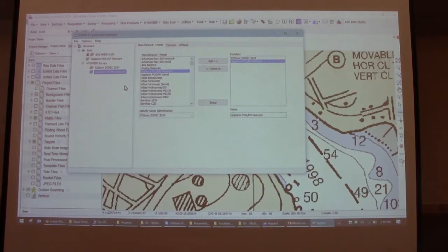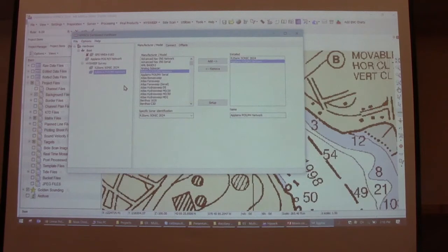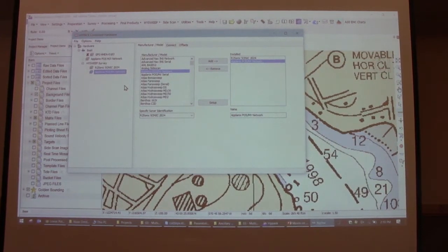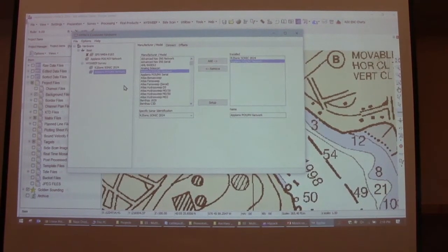Okay? Question. On your navigation, your GPS on multibeam, if you're running RTK, do you have to have RTK for your heading and position, or can you do differentially corrected in RTK? Can it be split up, or when you're running one RTK, do you have to run the other RTK? Say if you're using an R8 or an R6, an R10. Right. So, okay, one's giving you heading and one's giving you position. Is that the scenario that you run under? No, I'm single beam. So, okay. I mean, I have an R6. Okay. And I run RTK ties.